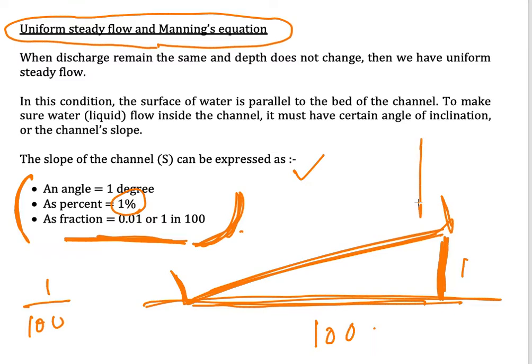If you have, for example, 30 degrees, you will create a very high velocity waterfall, which is not good because it could exceed the safety limit of construction. So normally people will use a very slight angle. If your answer shows a big angle, sometimes it is totally wrong.